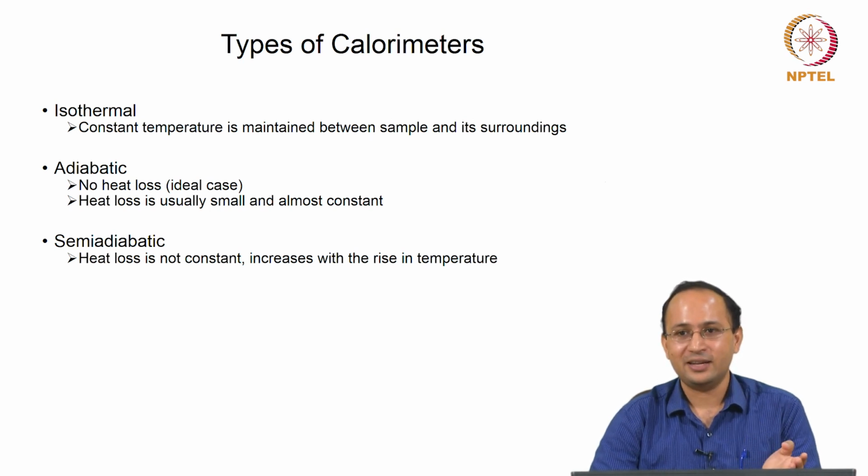Obviously when the cement hydrates, the temperature will increase because there is heat, right. If you can remove that heat, then you will be able to maintain the temperature. You are measuring the heat you are removing from the system. So that way you are monitoring this process.